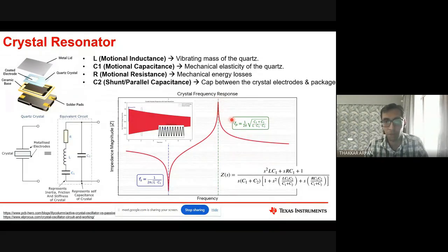If you have a wider quality factor, then you have a center frequency. Now some disturbance comes, it can easily go this side and this side, right? And this amplitude also will not drop so much. But now, if you have a very tight quality factor, and you have to move it a little to this side or this side, it will take a lot of effort. And if you try to move this frequency a little here, its amplitude is going to drop down and oscillation will stop by itself, right? So that's the thing, you need a very, very good quality factor.